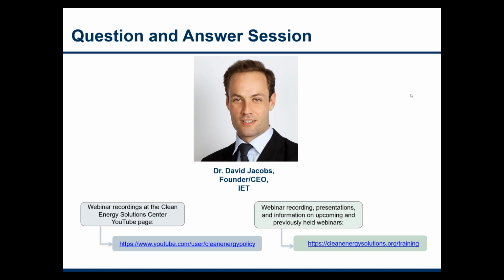DC into AC. What we actually see in many countries is that the modern inverters that we have are actually helping to stabilize the power system, because they can provide certain ancillary services to the power grid, such as providing reactive power, so helping to have a run-through capacity in the case of voltage dips. So this is actually no longer a real big issue. It just depends on how to program the inverters.